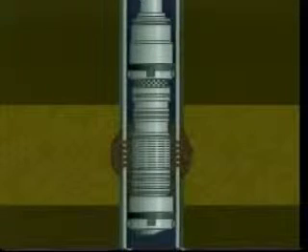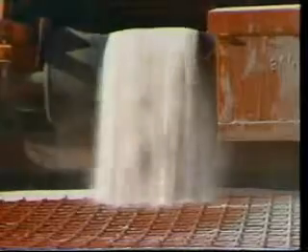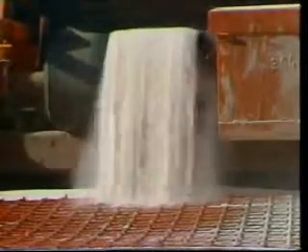The term gravel pack can be misleading, since it often refers to a uniform silica sand, such as the 20/40 mesh sand used in hydraulic fracture stimulation. When packed against the formation, this type of sand serves as a retention-type filter.